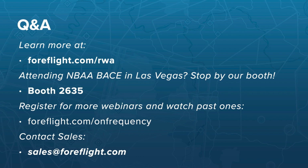Yeah, sure. Thanks, Sam. Yeah, so LDTA and in context with that as well as GRF, the global reporting format to support runway CC or runway condition codes. Both of those are being supported within ForeFlight already. So for the landing distance time of arrival calculation, you can use ForeFlight and update weather during your descent for actual conditions. We do support for some aircraft runway condition codes already. That is more of a function of the manufacturer providing us data to update that with. But ForeFlight's also offline capable for all these calculations, so we fully support those requirements. Awesome, thanks, Michael.